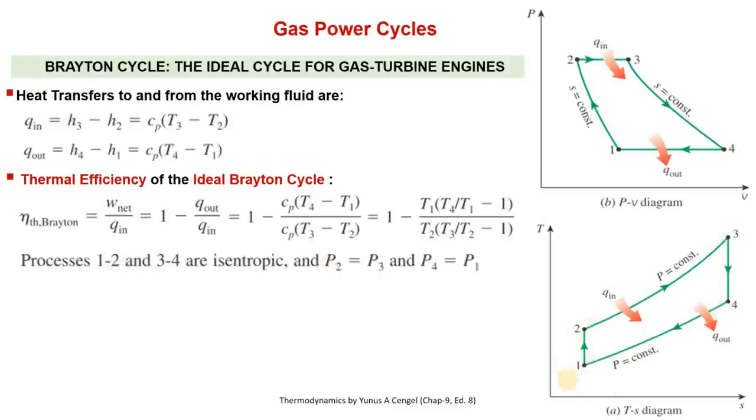Now for an isentropic process, we also know some more equations for an ideal gas and for an isentropic compression or expansion process. We derived these equations, right, for constant specific heat, for an ideal gas, and for an isentropic process. We can write this compression equation as this one, right? So this is something which we have derived in Thermo 1, chapter 7.